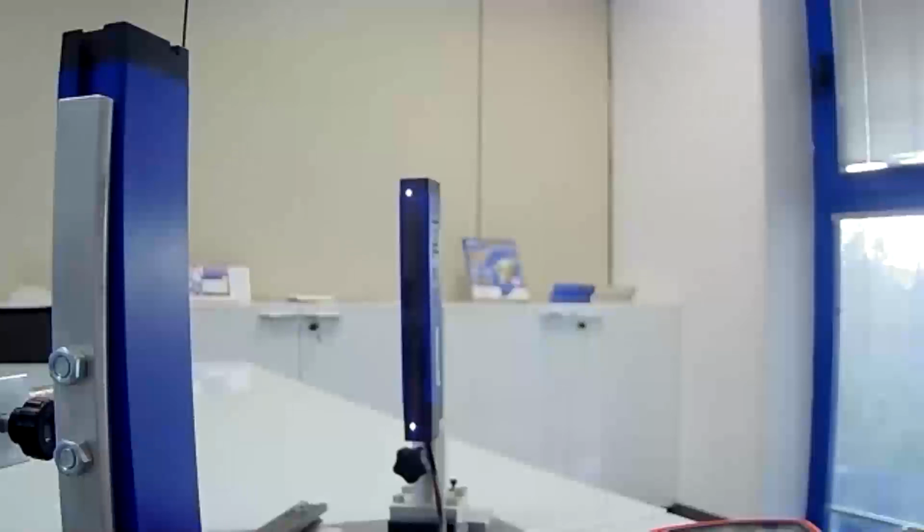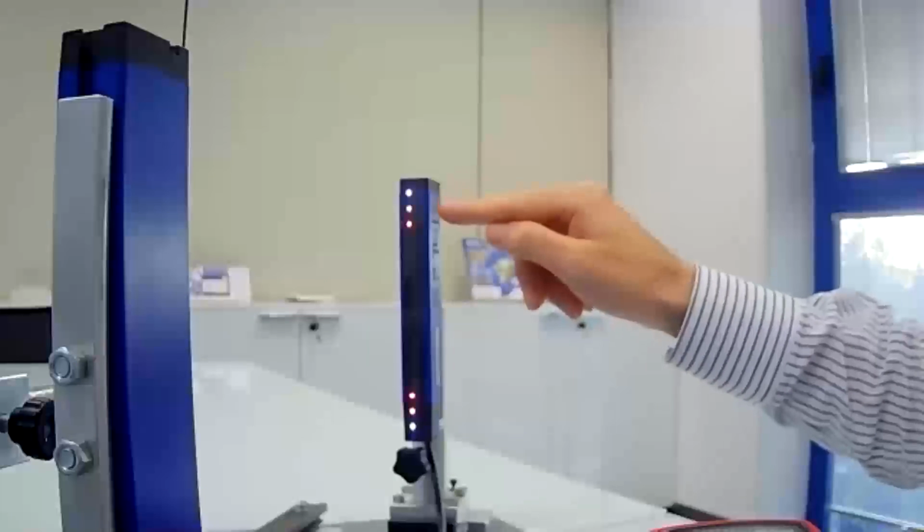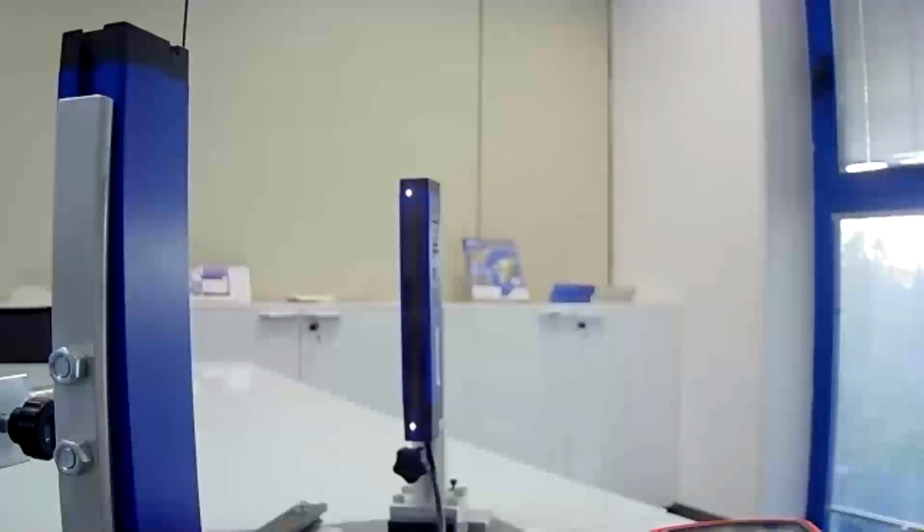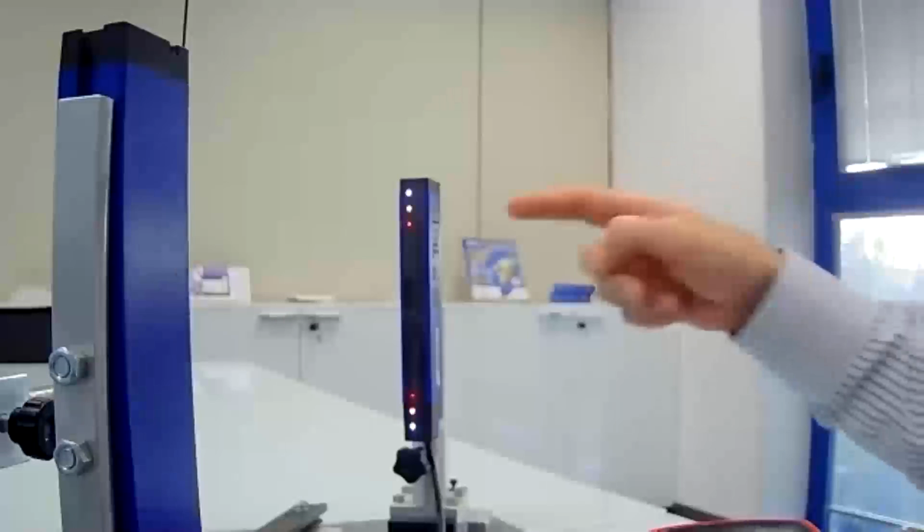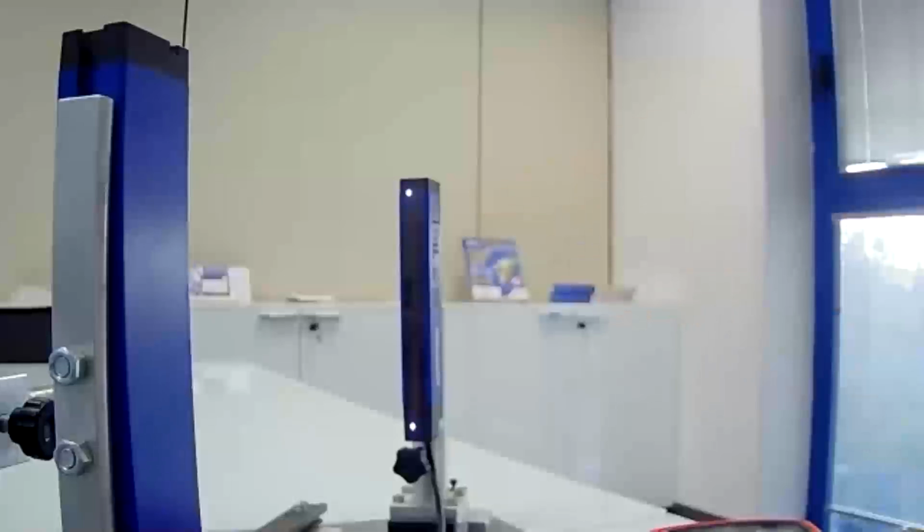Adjusting the sensitivity is very, very easy, because you just have to connect the setting wire to positive or negative for the fine or gross teach-in, and immediately the sensor is set. So you can now see that the sensor adjusts its sensitivity according to the working distance. You can leave this wire normally connected to positive or negative, and so at each teach-in, as you can see, it performs the setting procedure.